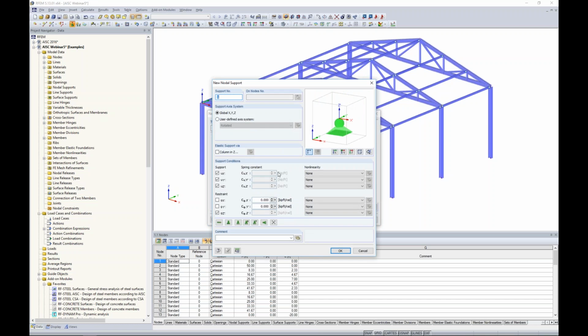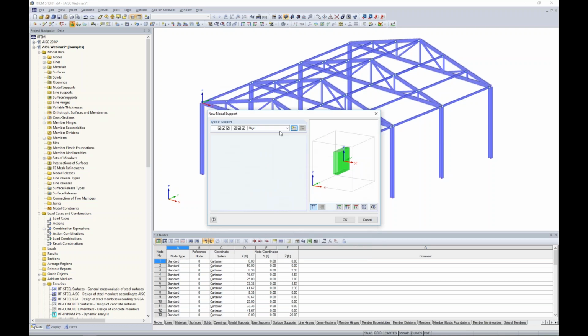Of course, you can create your new nodal support definition, and this should look quite familiar. This looks like our member end conditions. We have our 6 degrees of freedom. We have partial fixity here, and we have nonlinearity to take into consideration if we'd like. Now, nonlinearity might be important for sliding or friction supports. For today, we will stick with one of the defaults, which is fully rigid.